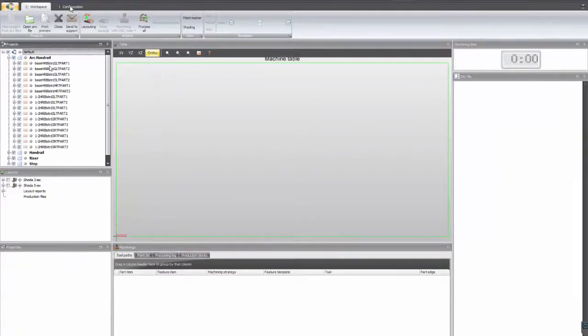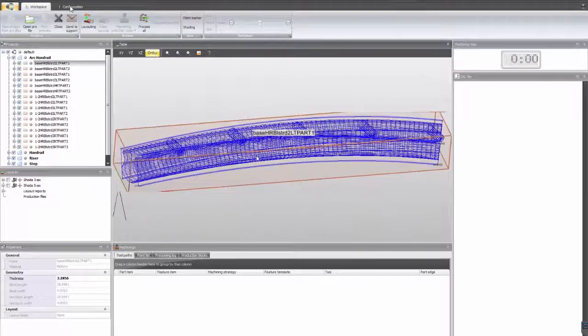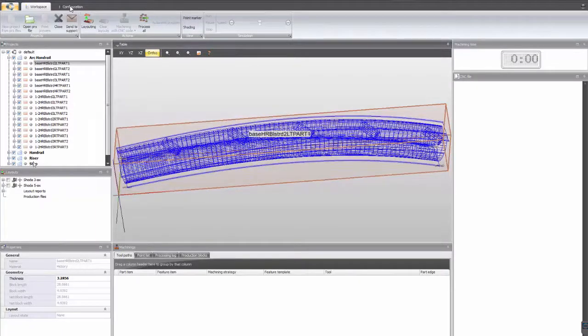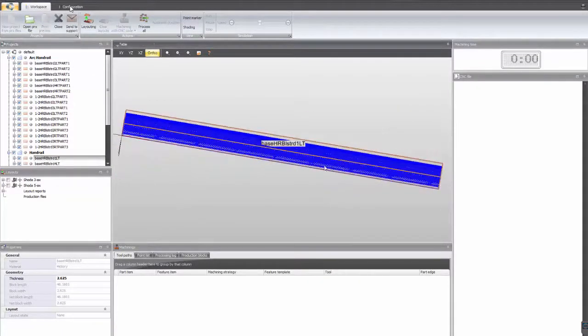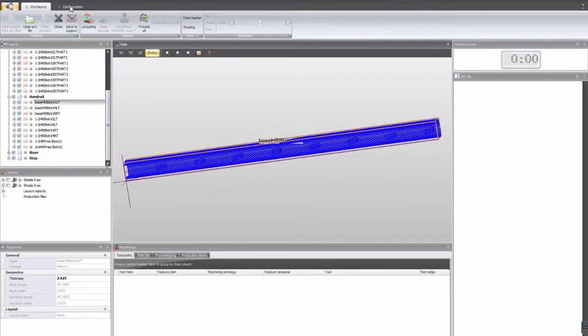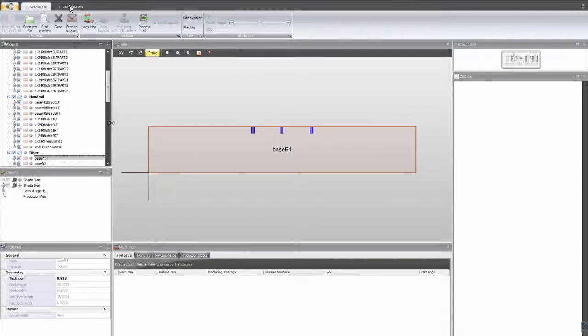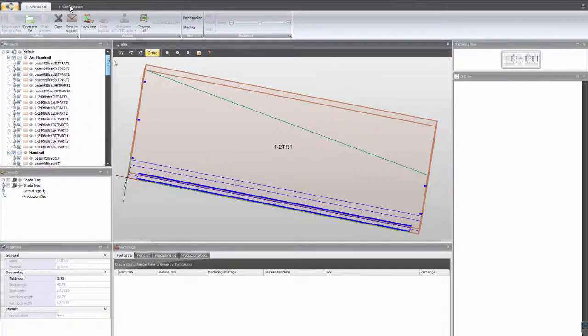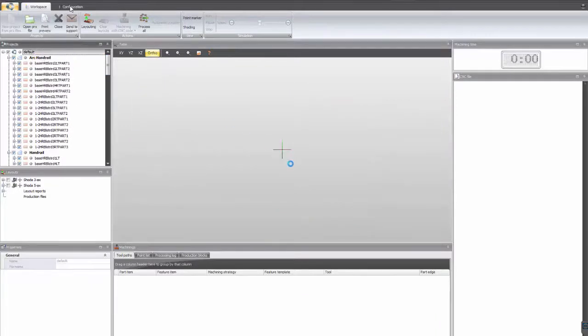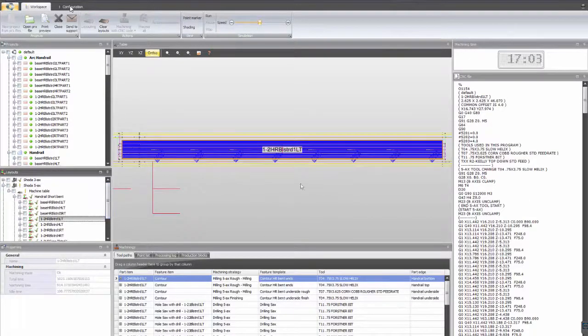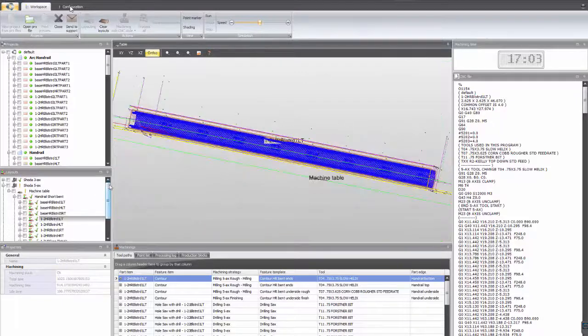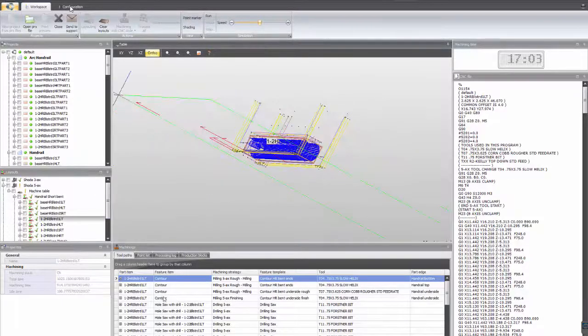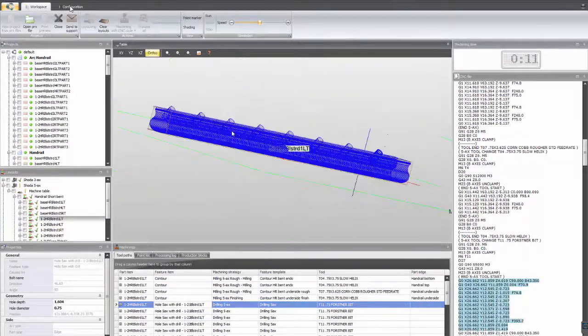And here I have wreath handrail drilled for balusters. We've got straight handrail here also that we'll process. Risers. And treads. So again, I'll calculate, process items. Okay, so I've got handrail here, straight rail. Let's get the profile on it. And it's drilled on the pitch of the rail, for the balusters.